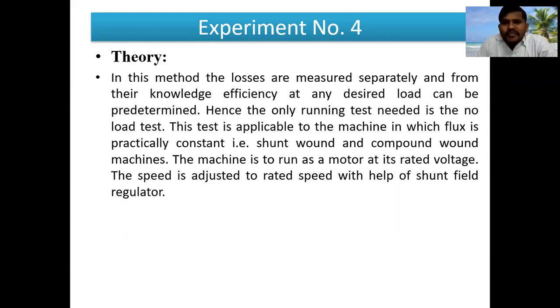or this method is used to measure only the losses, that is, only the no load losses. In this method the losses are measured separately, and from that knowledge the efficiency at a desired load can be predetermined. Instead of putting the motor on actual load condition, we are just performing a running test on that DC motor.